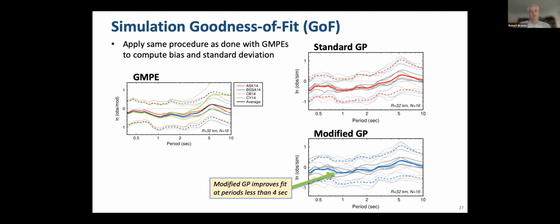But this is a very encouraging result, and it suggests that this is an effect or a feature that we probably need to account for, particularly when we have ruptures like Ridgecrest, where the fault, as it comes up to the surface, is very complex, multiple subparallel segments, probably breaking up new rock or breaking through new rock. So a lot of the energy of the rupture is being consumed doing that as opposed to going into ground motions. And that's what's changing the shape of the slip rate function, and that's reflected in the ground motions.